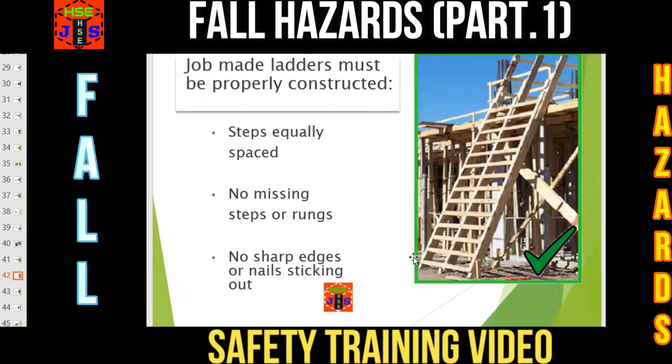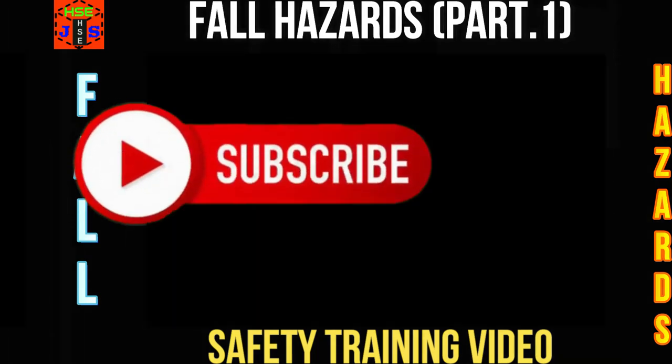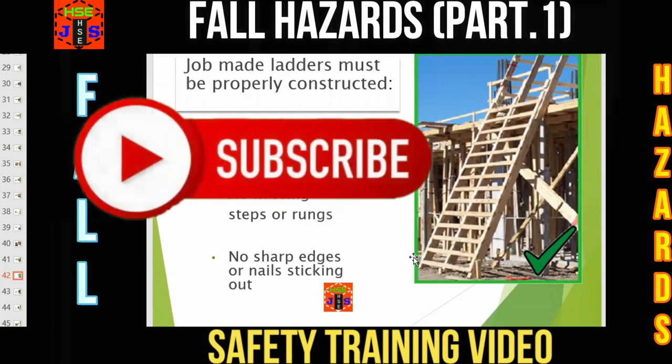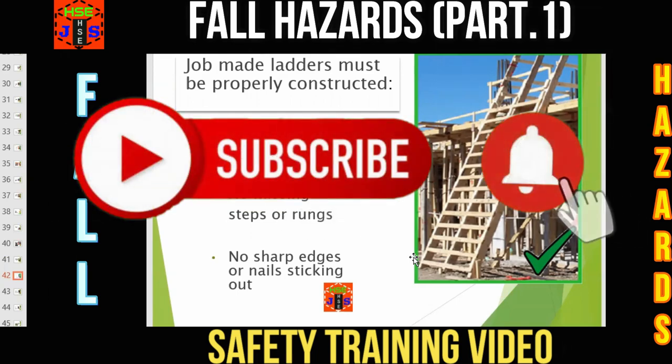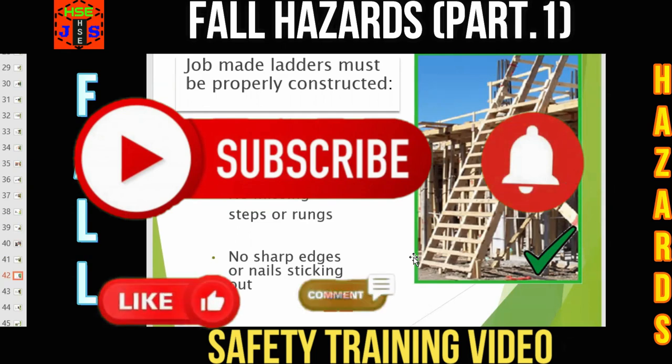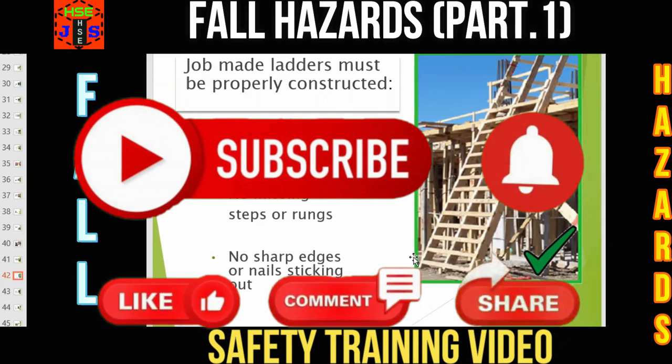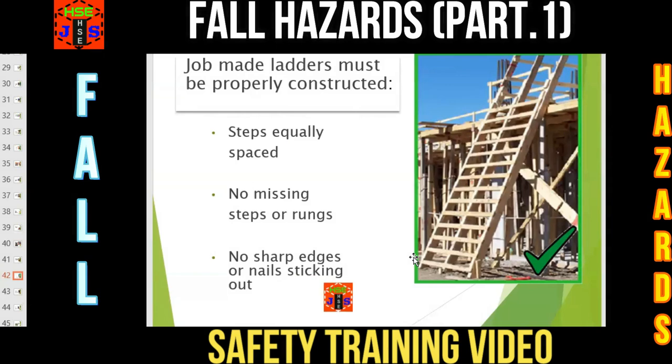It is recommended to use properly designed ladders with proper specifications and as per the instructions of the manufacturer. But if your site demands man-made ladders, then you have to look: steps are equally spaced, no missing steps or rungs, no sharp edges or nails sticking out.